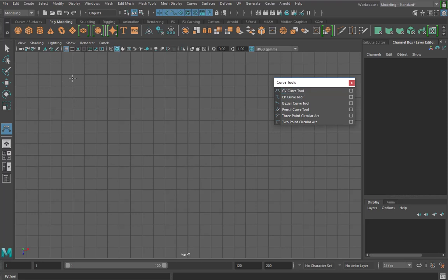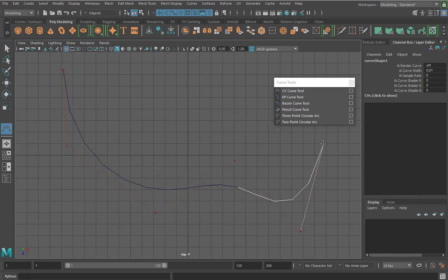To create a curve, I can simply click drag on the grid, 1, 2, 3, and as soon as the fourth point appears, the line, which is the yellow line here, appears. So that's basically the curve. And then again I can continue that.